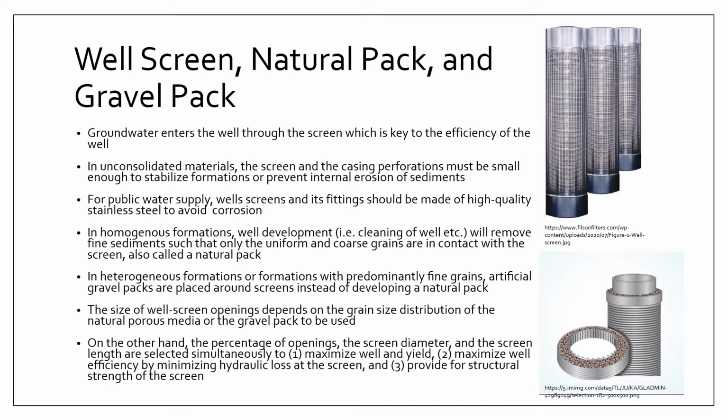All right, now let's talk about your natural pack. When you are dealing with an aquifer that is comprised of a more or less homogeneous formation, or an aquifer that might consist of just one type of lithology or soil type, let's say, for example, just sand, what we typically do in this type of formation is to do some well development.